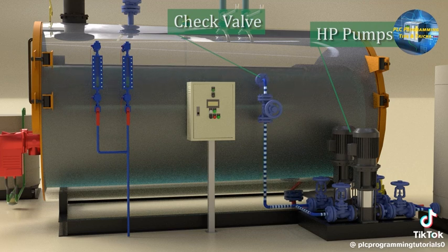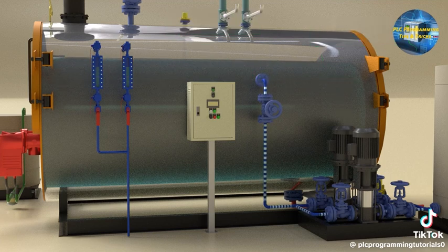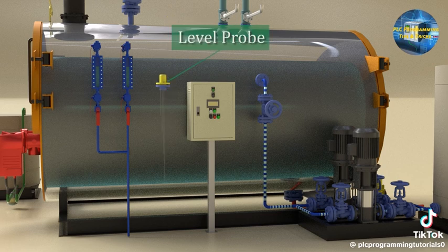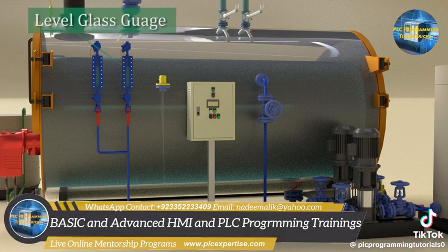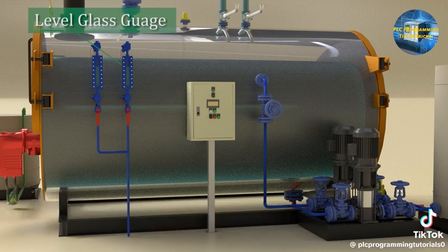Once the water level reaches the high level, the pump stops filling. A water level probe is installed in the boiler shell, which detects low level, high level, very low level, and very high level. This probe starts the pump at low level, stops the pump at high level, and triggers alarms and shuts down the boiler at very low or very high water levels. Two visual water gauges are also available for the operator to monitor the water level inside the boiler.